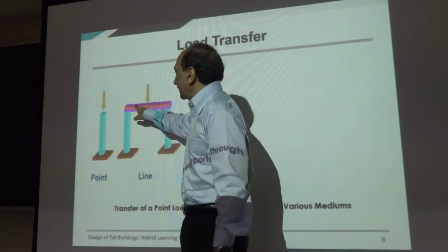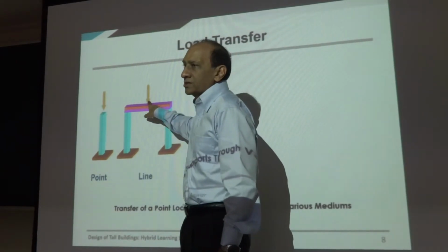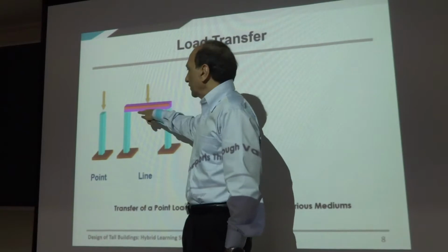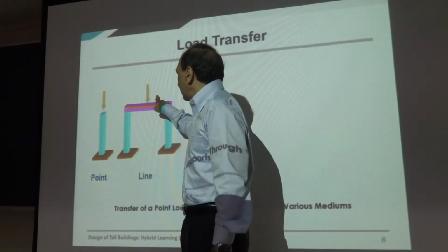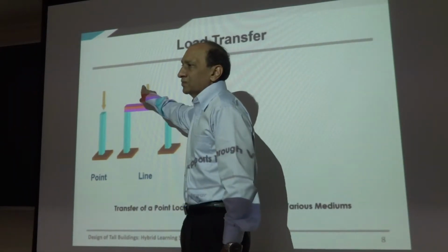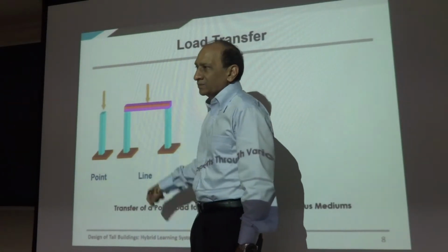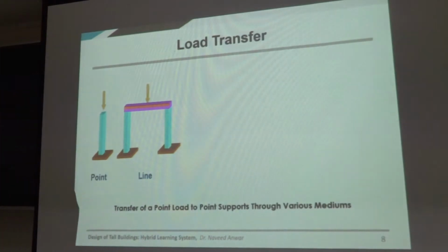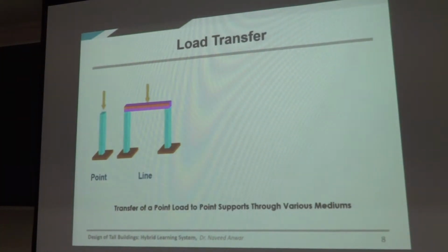So here you can calculate by hand based on the distance from the point of the supports. You know, this load is equal to this distance divided by this total distance multiplied by the load, and opposite, right? So based on that, you can calculate the loads directly. Correct?